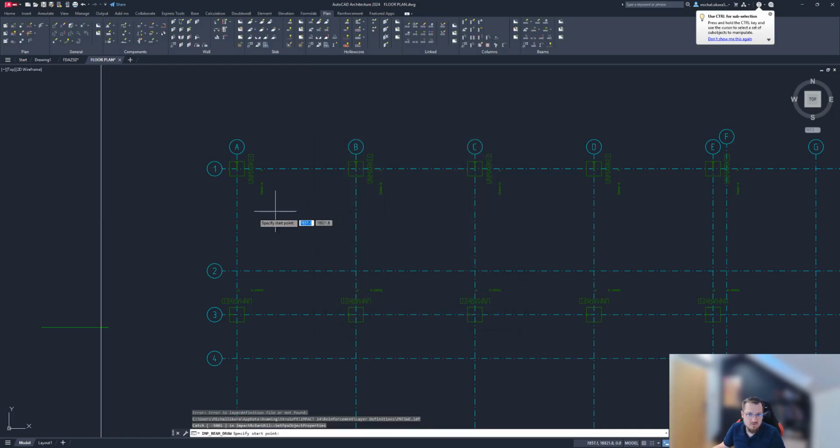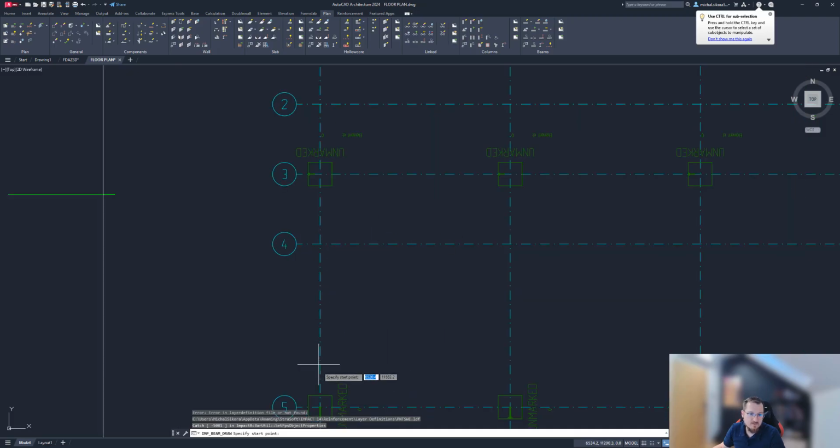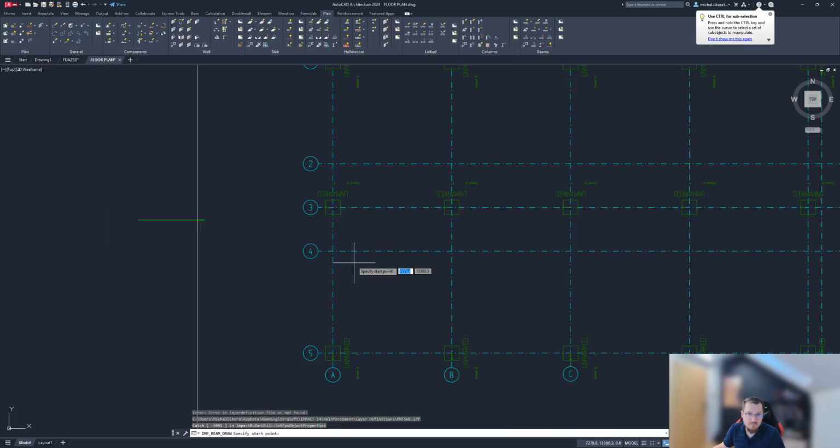One thing of note that's worthwhile to know is the direction in which you place a beam, a ledge beam, matters, and basically all the elements matter, because the direction you start putting the long elements, by say placing them along lines or polylines, determines where the front and back faces of the elements are, or left or right sides of those elements are.